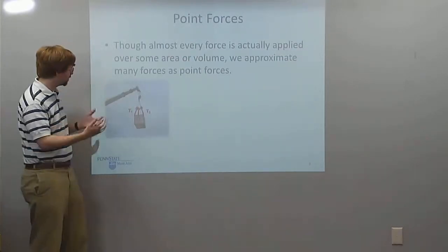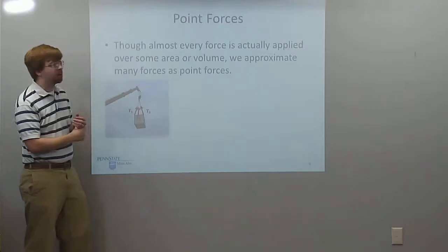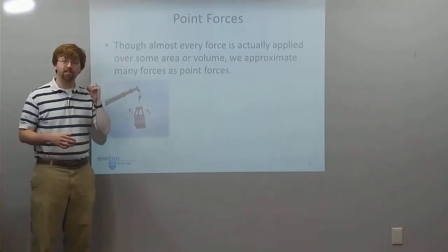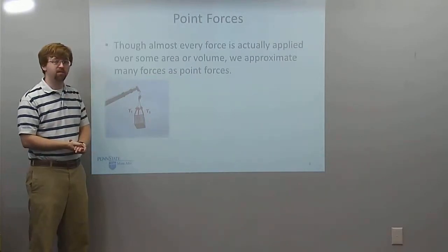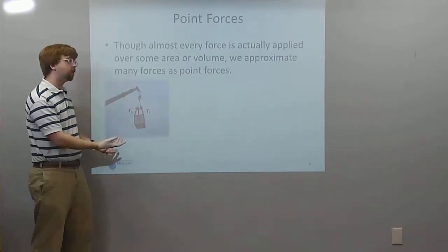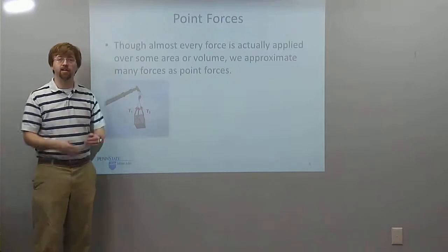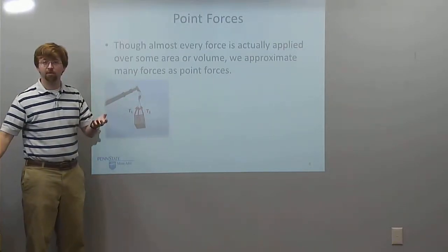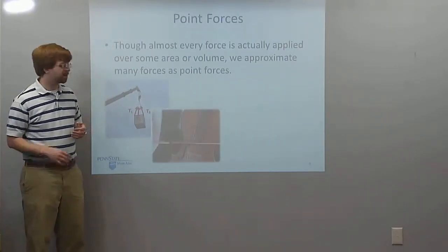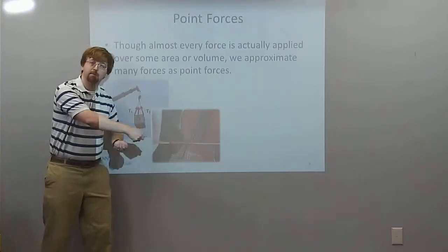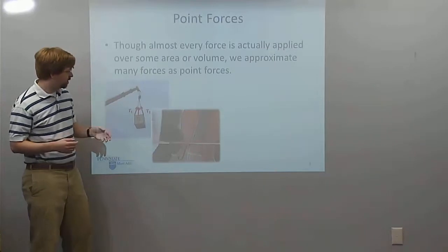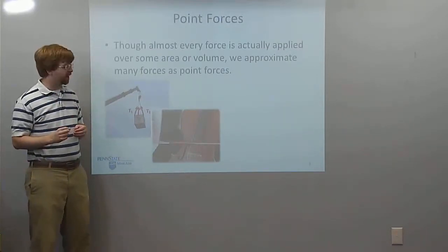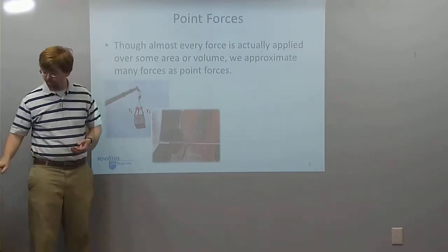So first thing would be something like tension in cables. The cable actually has some thickness or some diameter to it, so it's not a single point that we're applying this tension force to, but really they're so thin that we usually just approximate tension forces as point forces. Something like this friction force, we've got a bow being drawn across a cello here. There's a small area of contact there, but really we'd approximate this as a point force.